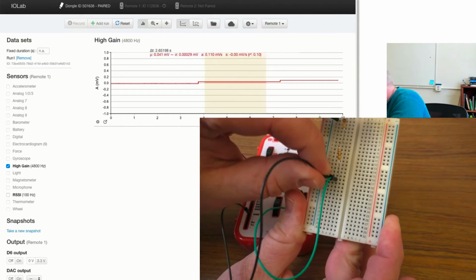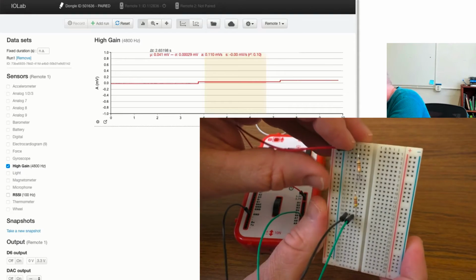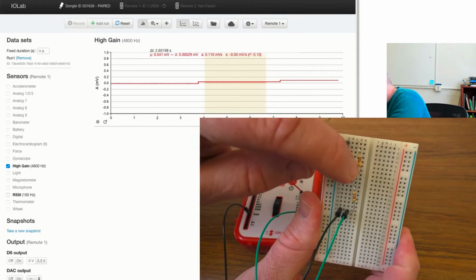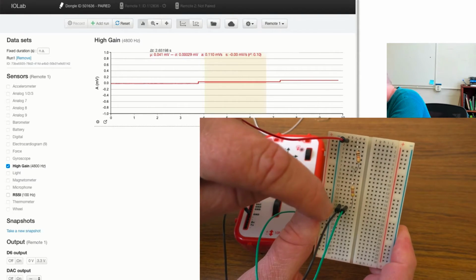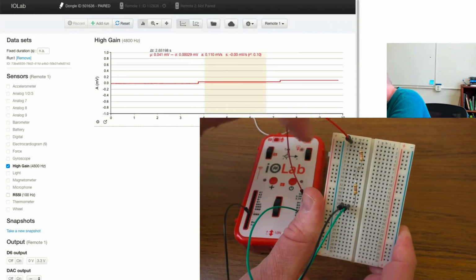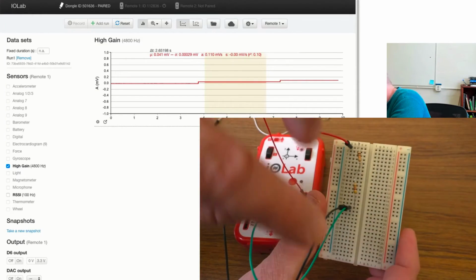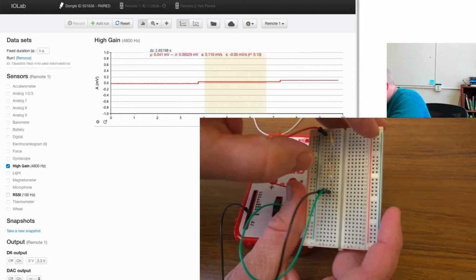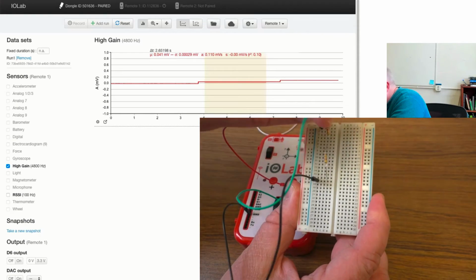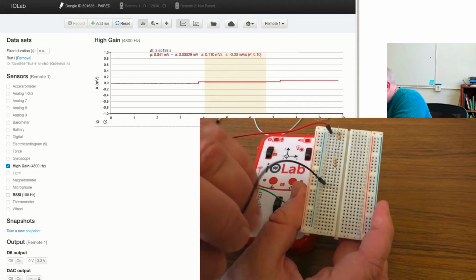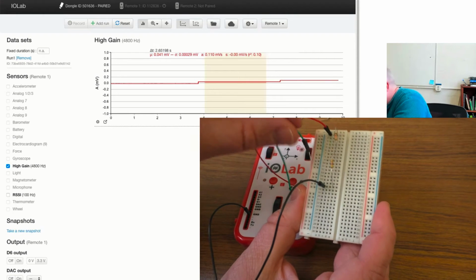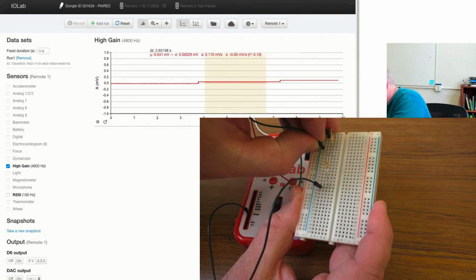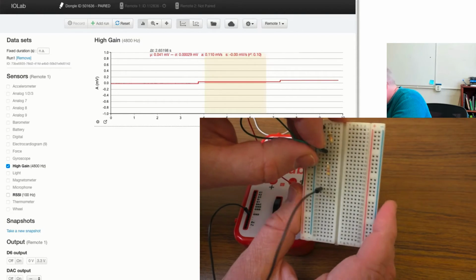All right, that way we have a pathway from the power through the first resistor, through the second, and back through the ground, completing that whole loop. And then, to measure the voltage over the 4,700 ohm resistor, I'll put the A7 sensor there in row 7.